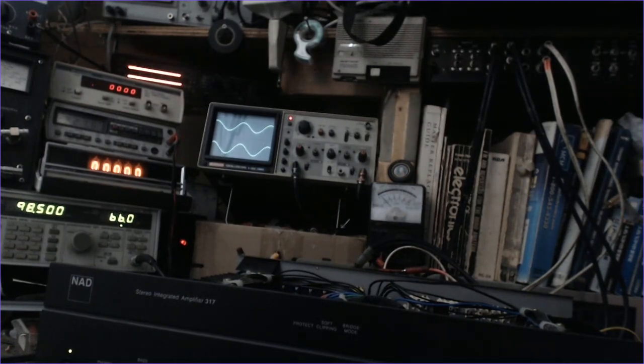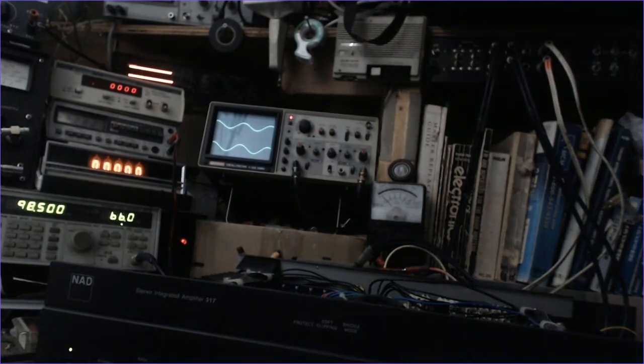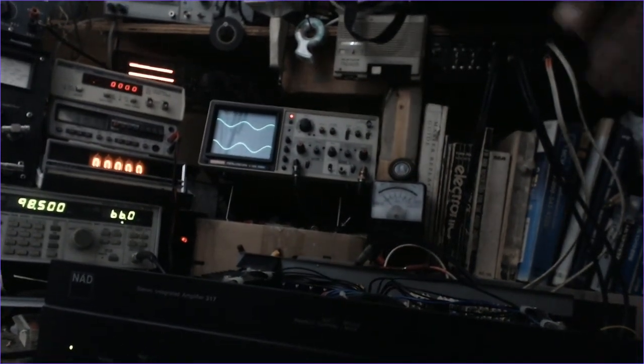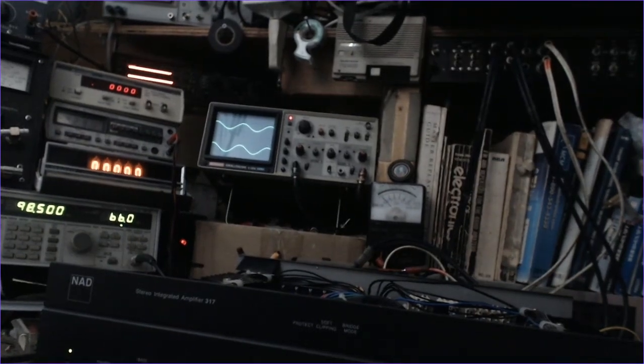So what I'm going to do is switch the speakers into what's called a dummy load. I'm doing that right now. Dummy load stresses the amplifier, same as a speaker, but it converts the audio energy into heat rather than sound. That way we don't blow up speakers or my eardrums as we turn the volume up. First thing let's do is run this bad boy to full power. And so I need to get some more gain here. Let me flip that down.